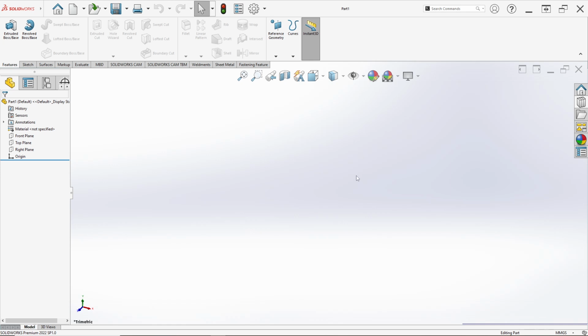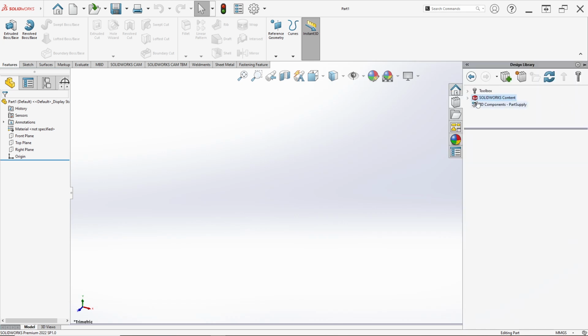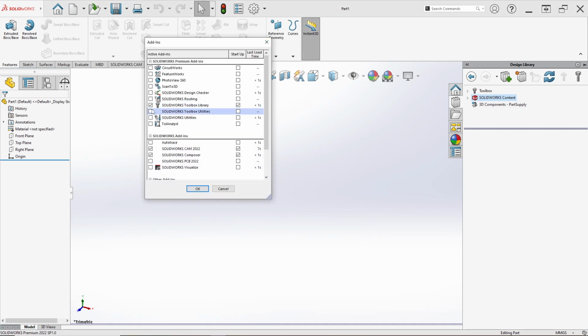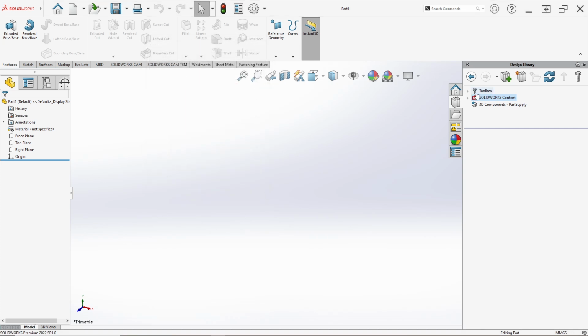This time, we will learn how to design a gear using Toolbox in SolidWorks. It's easy and fast. We start by selecting Design Library and choosing Toolbox. If the menu does not appear in your SolidWorks, don't panic. Just click the menu on the top and click Add-ins. Make sure the checklist is ticked, click OK, and SolidWorks shows the library. Just click OK and click Toolbox.